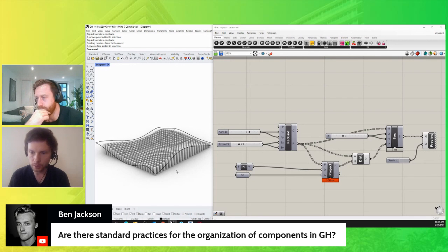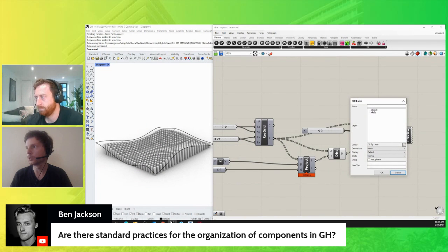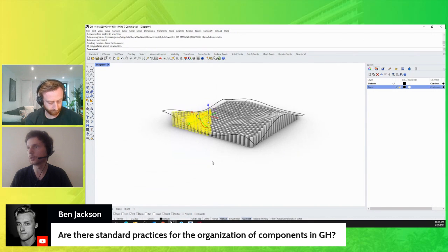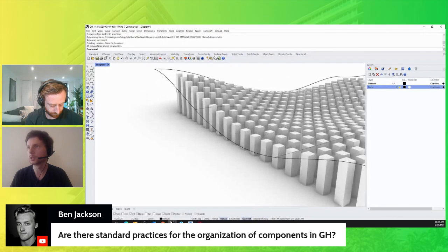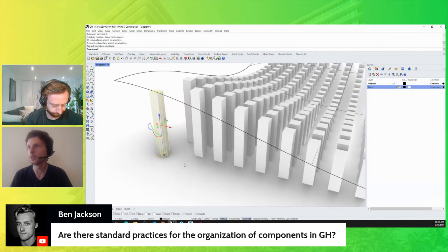I have to create the grid, then you need to bake the box. Yes, I didn't actually do that step, but if you right click here, all this geometry, I can't access it in Rhino. I just have the surface. So if I go in my box here and bake it, and then I'll put it in the default layer, I can turn off Grasshopper, and now my boxes are here. And their actual geometry I can start to manipulate if I want, in Rhino.